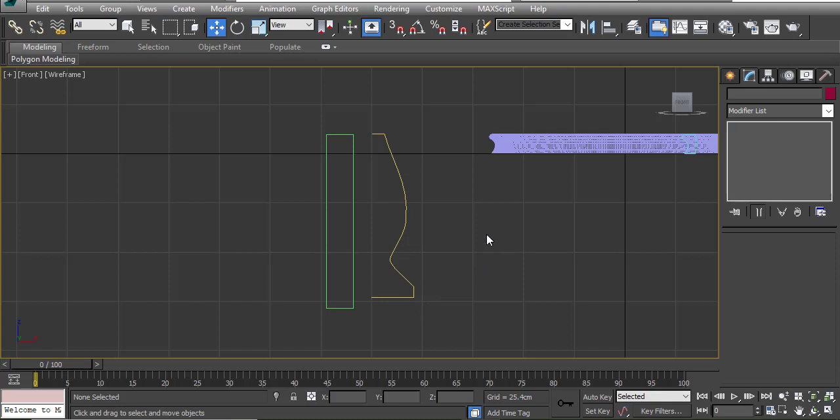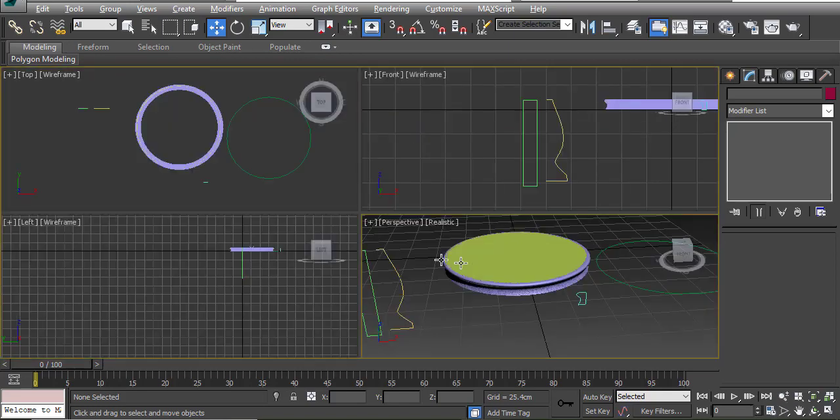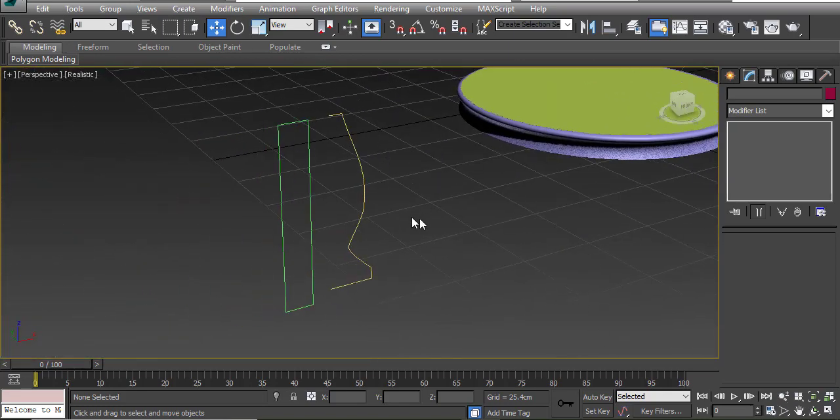because what we want to do is to use a lathe method. And with the lathe method, if you use this shape, the lathe will build a 3D shape around it. You can say lathe uses this edge to build a round shape like the same edge. Okay, let's use the lathe and you will see.